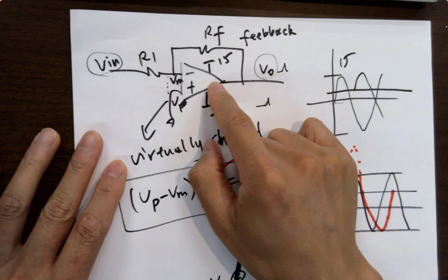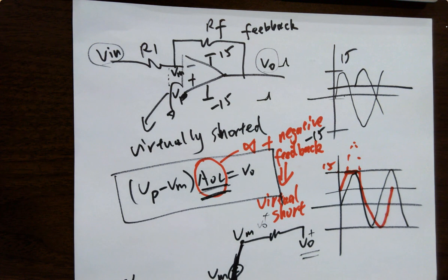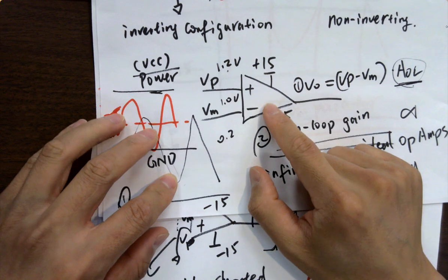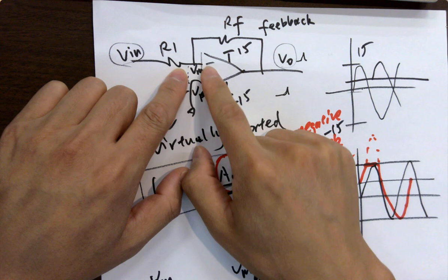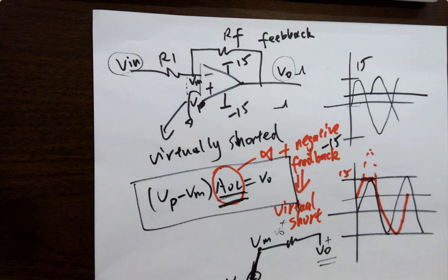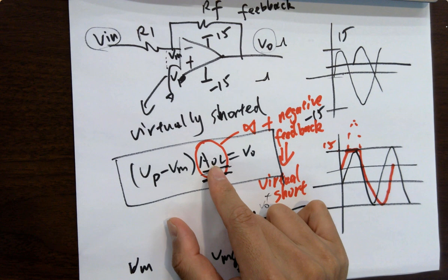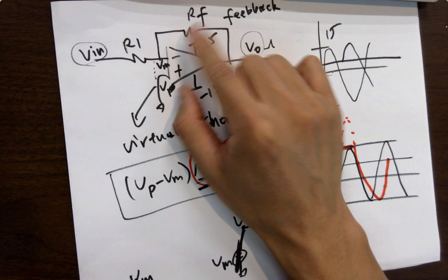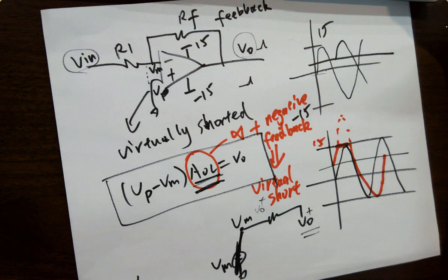But here this is equal. So the first thing you want, to make them equal, is what? What's the difference? Feedback, yes. What kind of feedback? It has to be negative feedback. So the first bullet point is negative feedback. What's the second one? If you don't have an infinite open loop gain, for example it's only 2, 3, 4, are you able to give that feedback super quickly? No, the gain is too small. It won't be able to provide that powerful feedback super quickly.